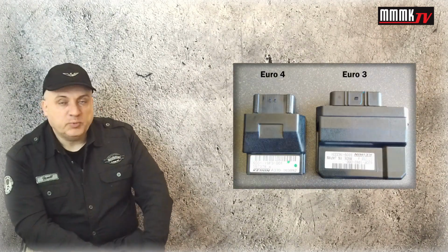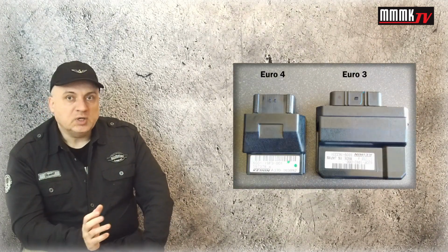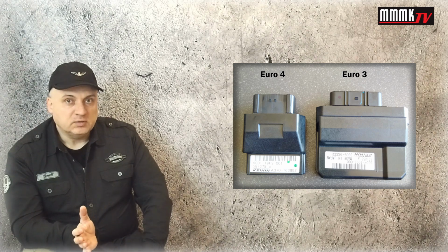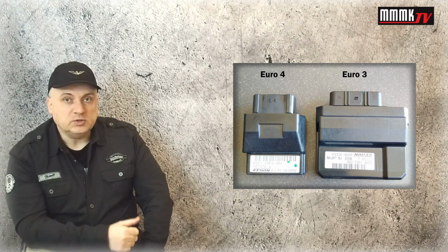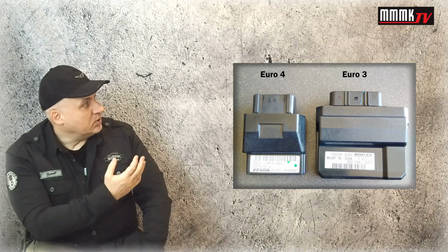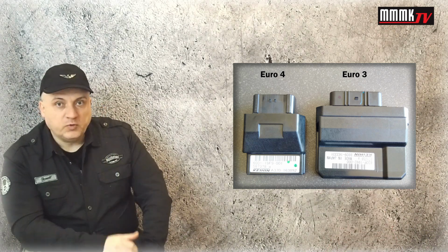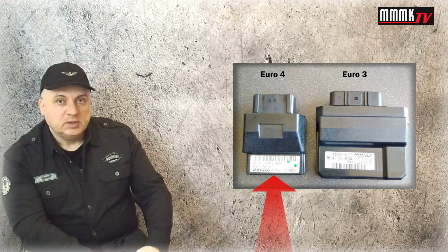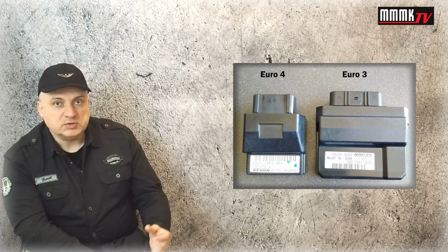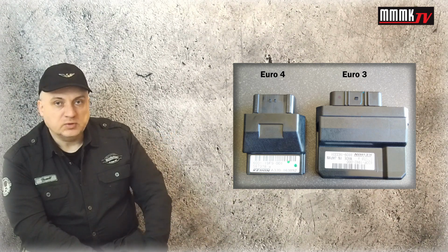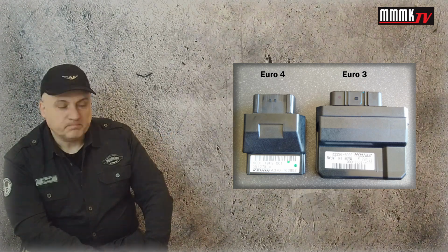Basically, important information: you can go down to the domestic ECU, we call it Euro 0, only when you have a Euro 3 ECU on board. If you have Euro 4, the small one, that wouldn't be possible because the connector is different. The connector is not compatible.